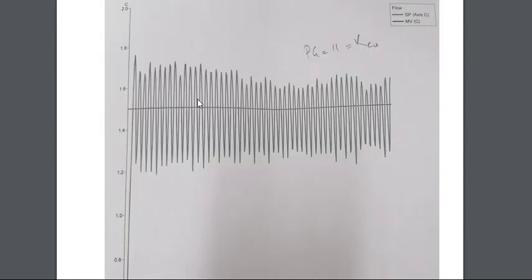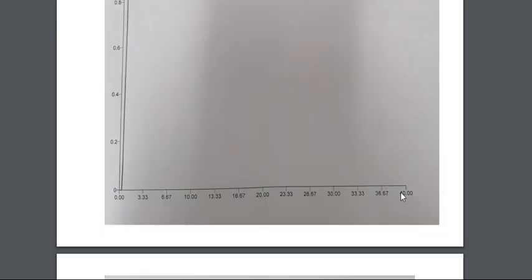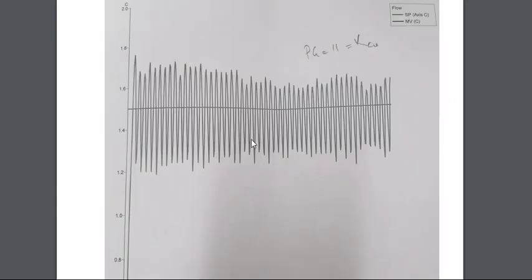Luckily, at 11 you can see that within the time reference, which is 40 seconds, the system is permanently unstable. So at this condition, PG equal to 11, we have obtained permanent instability. By implication, the PG now is the KCU, the ultimate gain. So the ultimate gain of this control setting is 11. Now we want to enlarge the scale by taking a smaller time interval of the scale.